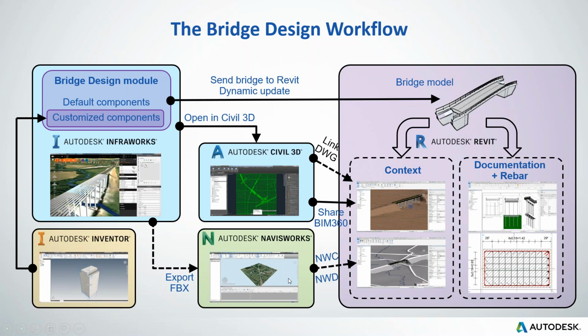We can push into Navisworks using FBX, and if we need to push more data into Revit to have the context while doing the detailed design, there are several ways. We can either push a DWG into Revit, but this is a dotted line.